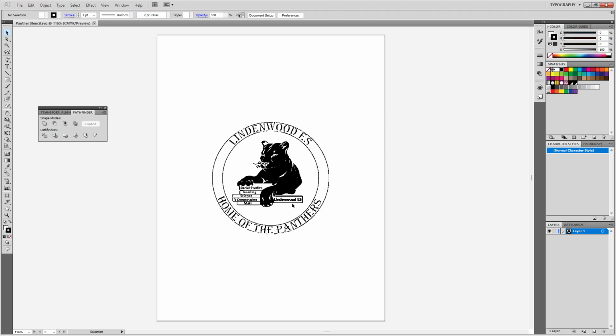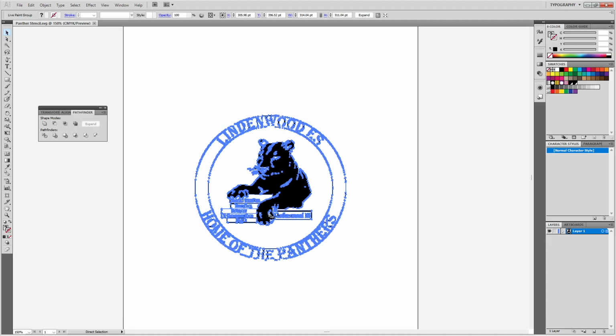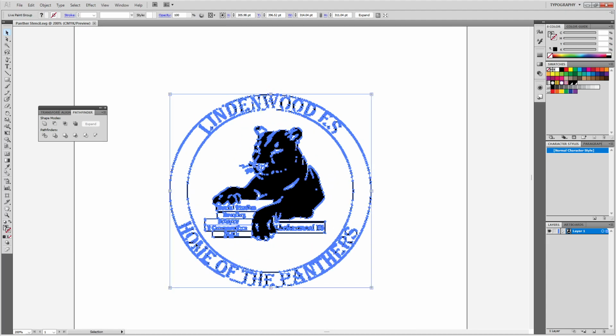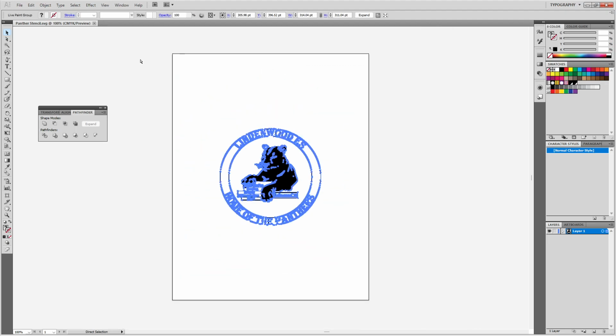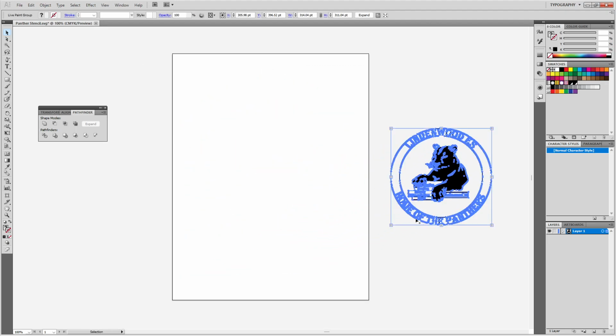But I want to share with you how you can either vector this by hand, or you could have Adobe Illustrator vector it for you, something called Live Trace. This is a completed sample of Live Trace, where it breaks all the line work down and creates a vector of the line work. So every element here is now a vector from the original drawing. But let me move this out of the way, and I will definitely start from scratch.